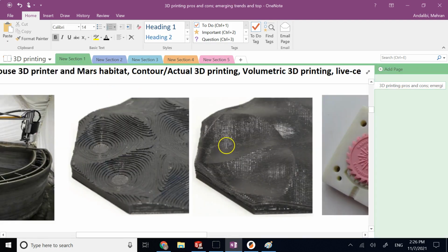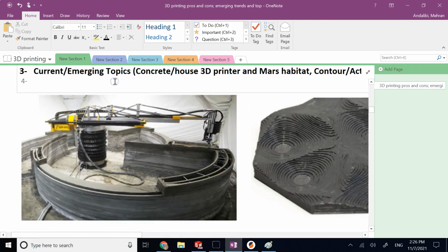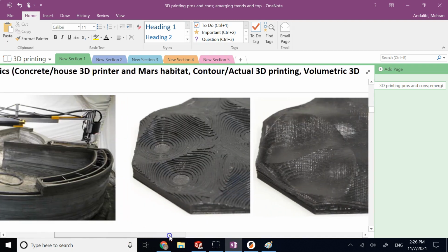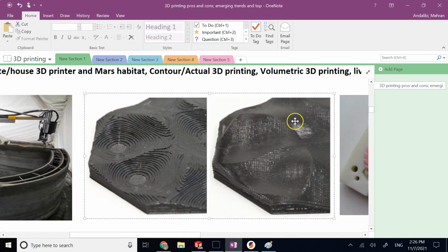So one of the things that they're working on is, during the 3D printing, the head of the 3D printer does not stay at the same Z and do all the deposition of plastic on that XY plane and then go to the next Z, which by the way we call a 2.5 axis machine. What it does is actual 3D motion.